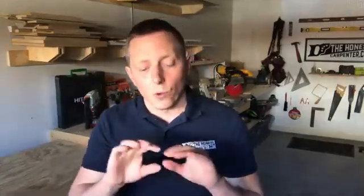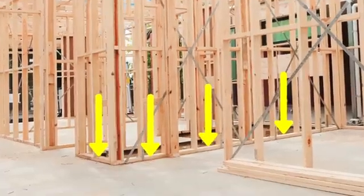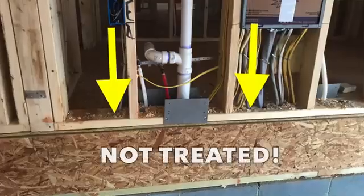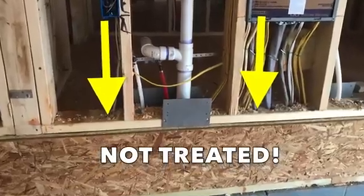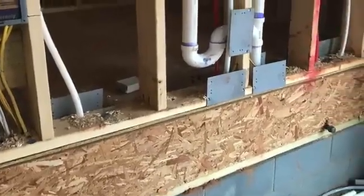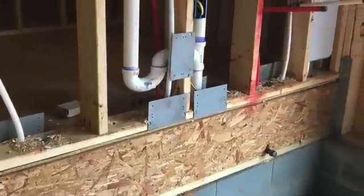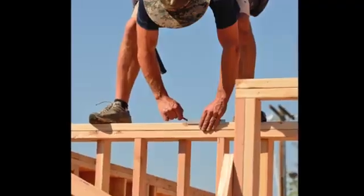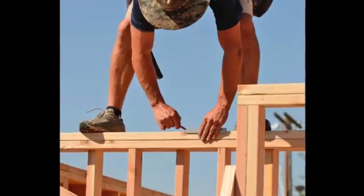Instead, they sit on another horizontal piece of wood known as a plate. A plate is basically just a stud laid down on its back. It's virtually identical to a mud sill, except that it's not treated because it's not in contact with wet masonry. This is just kiln-dried 2x4 or 2x6. So you have a bottom plate beneath the wall, and you have top plates at the top of the wall. Top plates are typically doubled up for strength. We call them double plates.